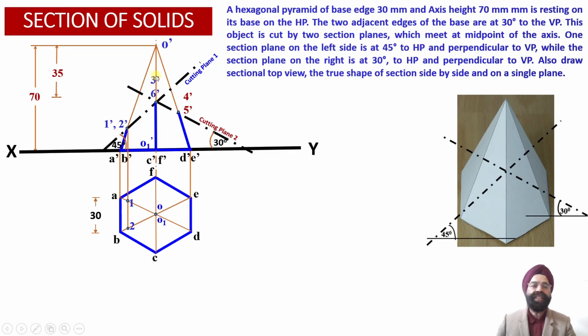So from points 3' and 6', as we are going to look at the solid from the side view, these 2 points will be projected or transferred onto the projectors O'A' and O'B' at 2 points, that is 3'1 and 6'1. So the 3'1 point corresponds to the point 3', and the 6'1 point has been obtained corresponding to the point 6'.